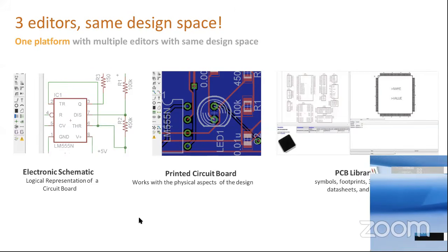Board layout editor and the schematic editor in Eagle actually work in real time together. That's what we call forward and back annotation. Modifications performed in the board layout editor will back annotate to the schematic, but we always prefer that you make the modifications on the schematic, like changing components, updating the libraries, as well as adding or deleting components. It needs to be done on the schematic. That way the board layout can catch up.